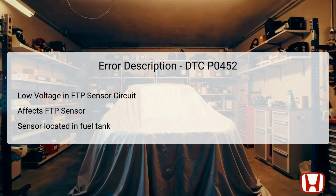The DTC P0452 indicates a low voltage condition within the fuel tank pressure FTP sensor circuit. The primary component involved here is the FTP sensor itself, located in the fuel tank. This sensor is responsible for monitoring pressure variations in the fuel tank and helps detect potential leaks, ensuring the vehicle complies with emissions regulations. A malfunction in the FTP sensor can lead to inaccurate pressure readings, which can impact the engine performance and increase emissions.